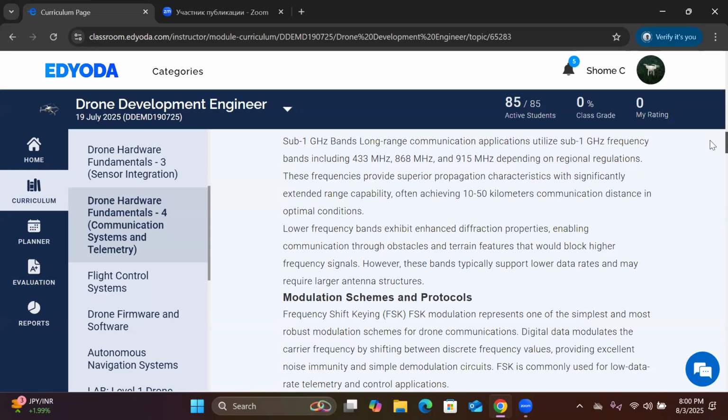Frequency hopping spread spectrum is basically a technology in which the frequency is modulated through different bandwidth schemes. That bandwidth scheme will be defined by the user. Now if we need to use a drone swarm of 10 drones, we have selected a certain frequency band, and that frequency band is divided as per our FHSS scheme.